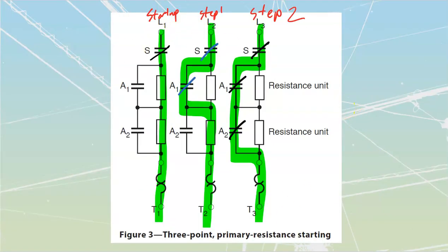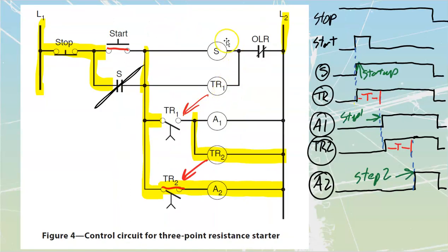You know, when we start up, we go through the startup sequence. However, if I would lose this thing, it could never remain inside there because this timing relay will finish up, which will power through to this one, which will finish up. There's no kind of manual where I have to press a button and increment this along and increment this thing along. It's all going to be automatic. And as soon as I would lose my circuit over here, hit the stop, I would shut them all down simultaneously.